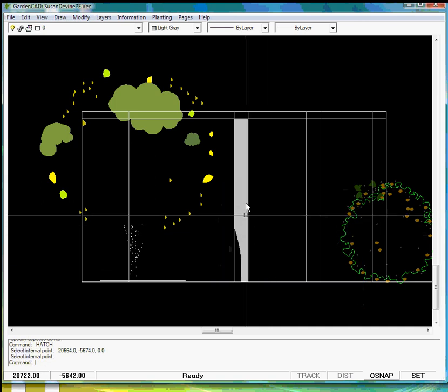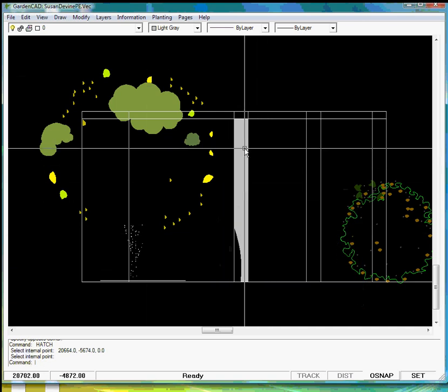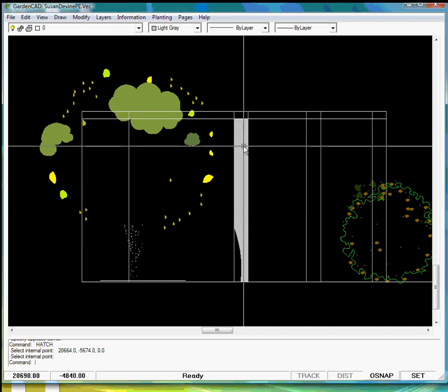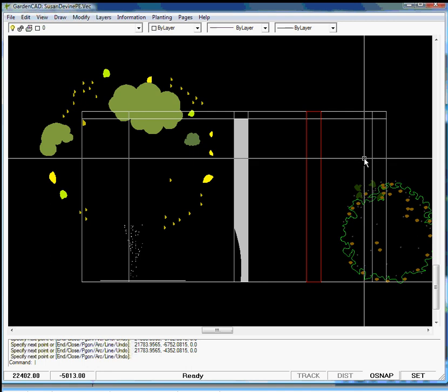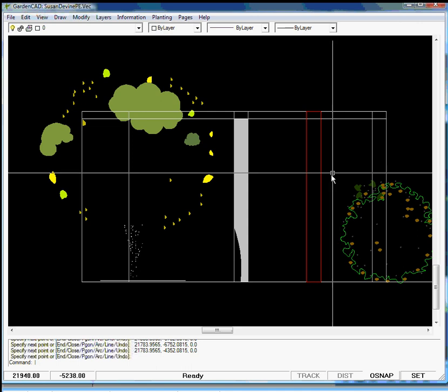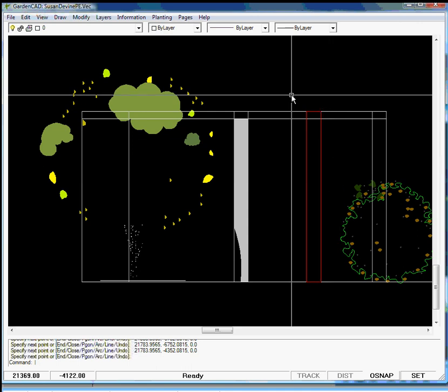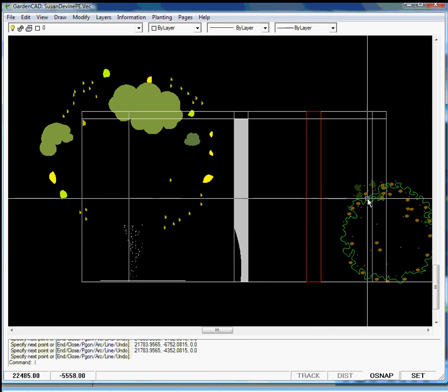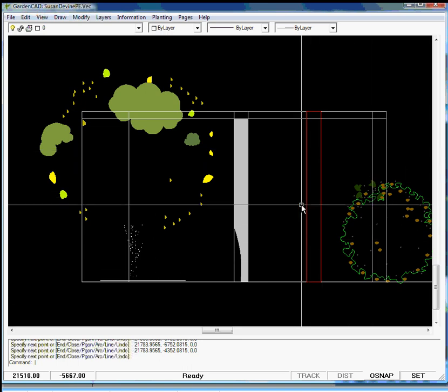So now that pole gets filled with the drawing colour, but can you see we miss that zone through there. This will be a bearer at the top there, of course. So here's the pole. Well, a more controllable way to hatch, especially when you've got tricky zones, is to draw a polyline around the area that you wish to hatch, and I've done that on a layer called hatch, and I've set the drawing colour to that layer to be red so that I can see it. So I've traced over the pole that was white on layer 0.